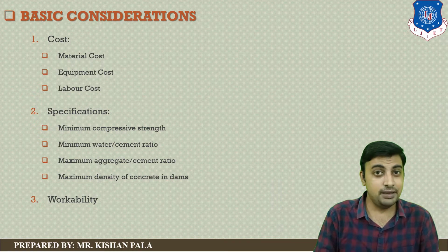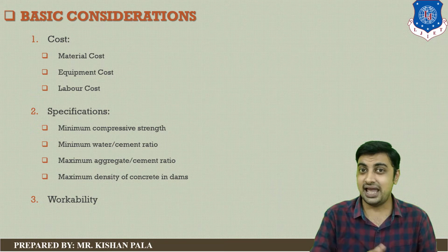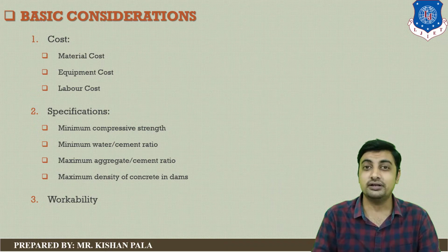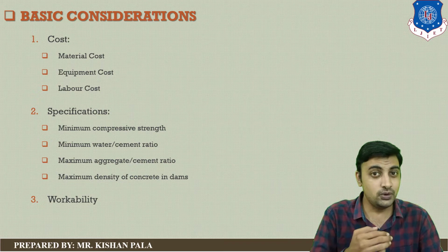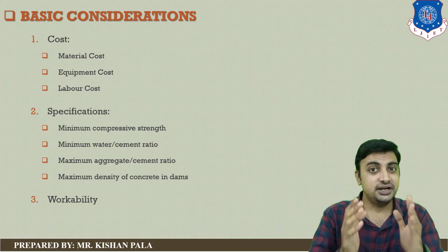Rather, you can use plasticizer and superplasticizer to decrease the water requirement. So you have to consider this point while you are doing the concrete mix design.